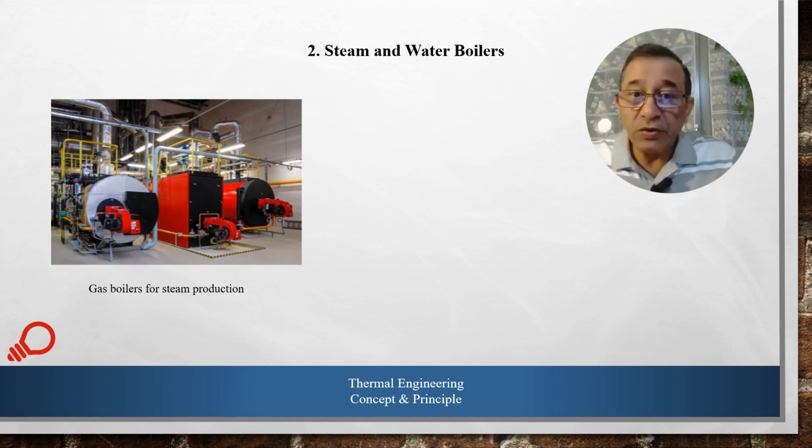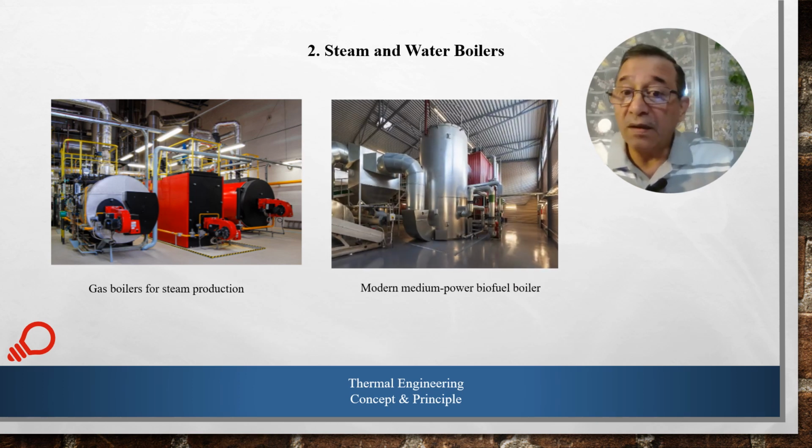These boilers use external energy from fuel, either liquid or solid, and burn it, get the output energy, convert water to steam, and then I will get it at the exit side of the boiler to use it for heating or as a service fluid in utilities. We may get water as well instead of steam, depending on our application, and usually it's used for heating purposes.